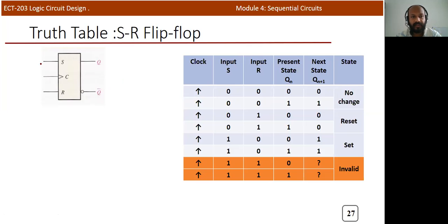If you take the SR flip-flop, the first possibility is that the SR inputs are 0, 0. There are two input lines, S and R, and assume that initially the Qn output is 0. After applying a clock pulse, when there is a positive edge, the inputs are sensitive and there will be a change corresponding to that.